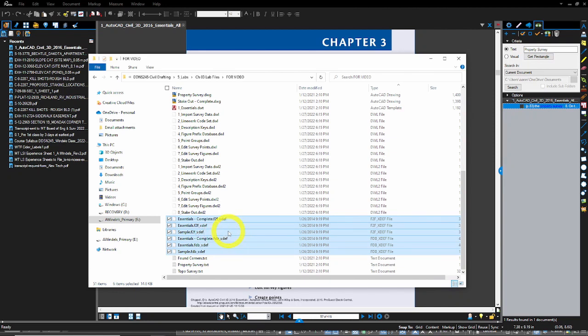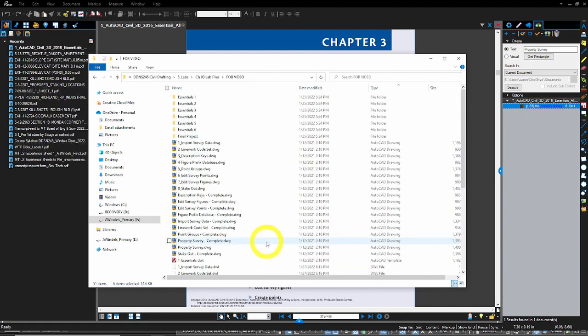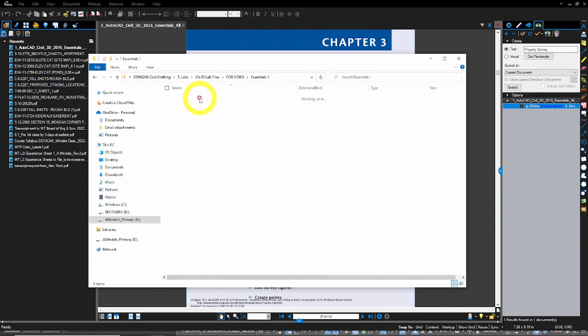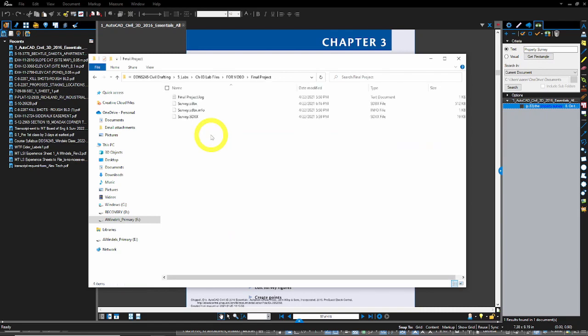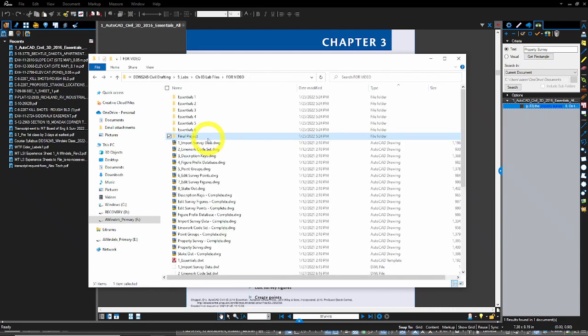They're definition files that go along with our Civil 3D survey database. These are survey databases. These will give you trouble if you have a newer version than 2019, but for all intents and purposes we'll be able to get through this. They have these inherent XML or generic type files in them that establish the survey database information outside of your DWG CAD file. From 2020 on, these files change a little bit, get a little more robust.